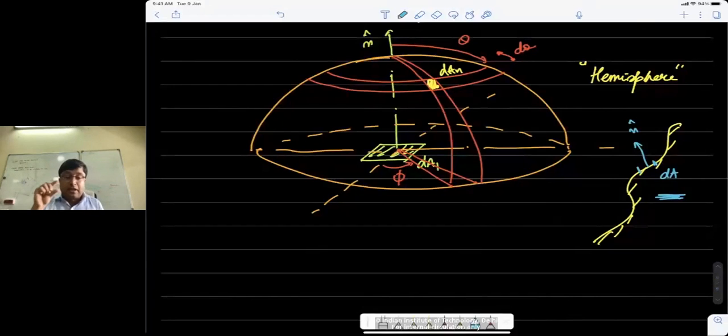I mean, if that was true, then of course we would have to. But as I said, even a body which is radiating from the other side, even if it's a plate, for instance, that plate has a finite thickness. And so what is going on down is not the same as what is leaving from the top surface, because the radiation is going from the surface only. So you can imagine that the surface is a very thin layer. So radiation is going up from the top surface, and you have to do the bottom surface analysis separately, not as part of one complete analysis.